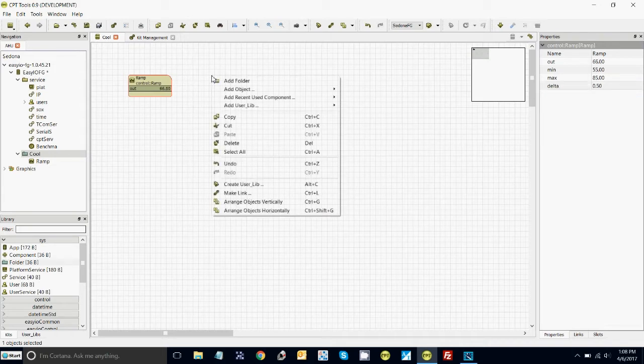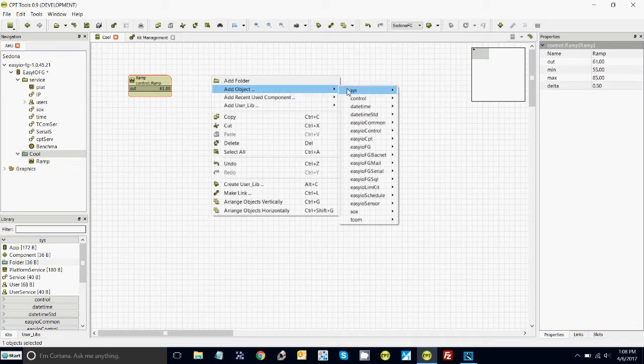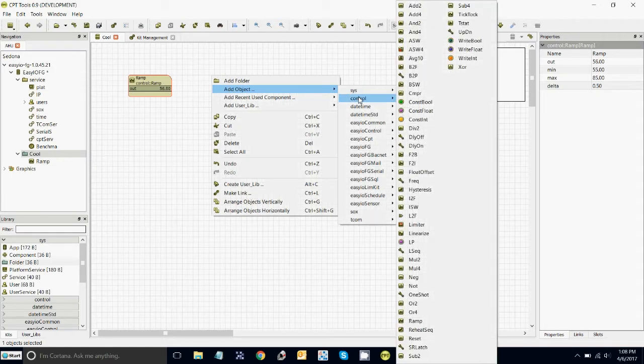So let's now add in a thermostat. So you go to the control block. Again, if you want any documentation on any of these, you go into the FG user docs and look for the standard, open standard Sedona kits. I'll show you again in a moment because it's super important that you use those documents. So let's go down here, find a T-stat, there it is.